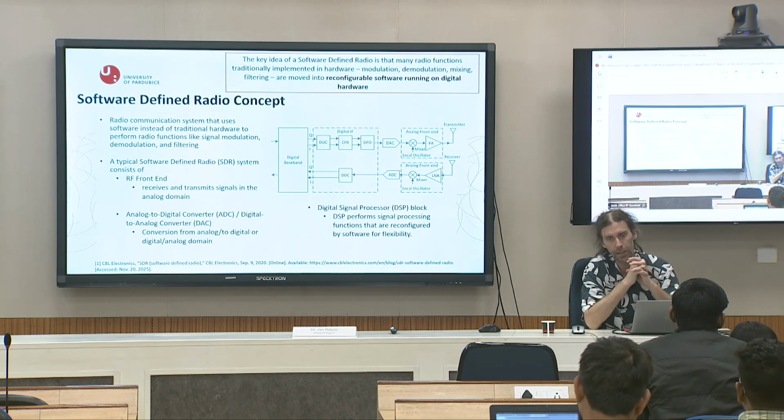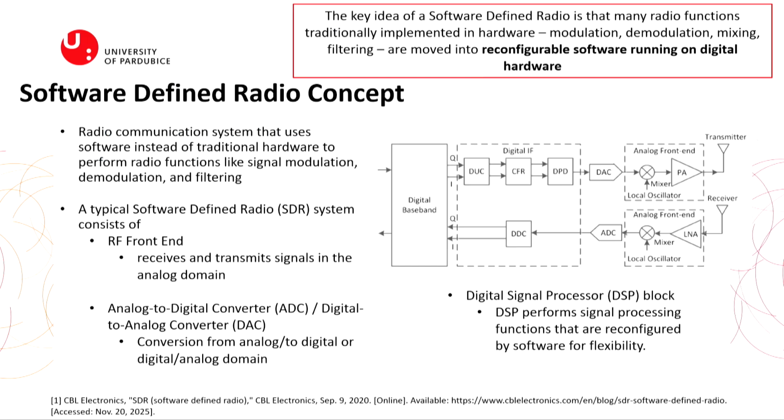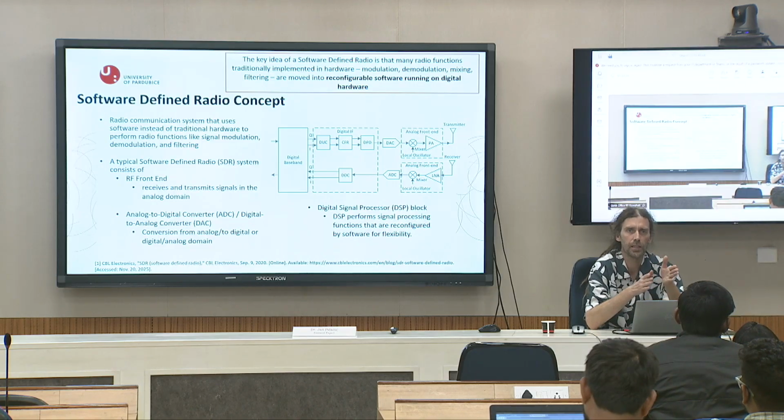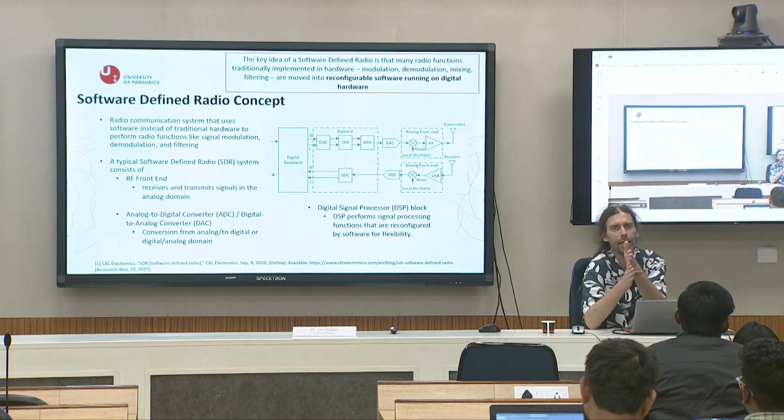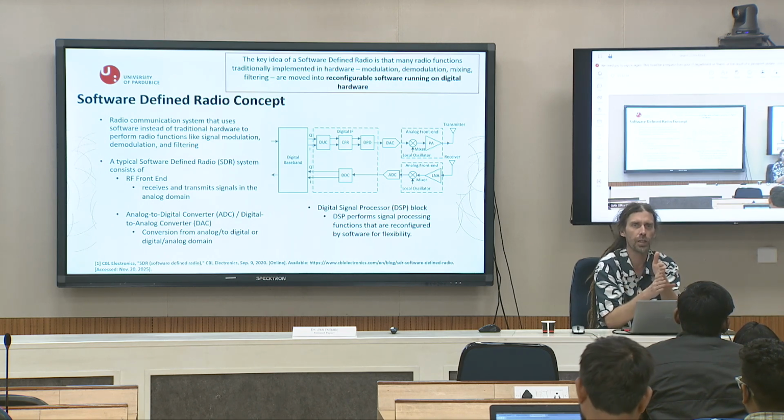I will spend two or three slides on the software-defined radio concept. The key idea of the software radio concept is that many radio functions which were traditionally implemented in analog hardware, like modulation, demodulation, mixing, filtration, were moved to software. For this reason, you want to convert to a digital signal as soon as possible.